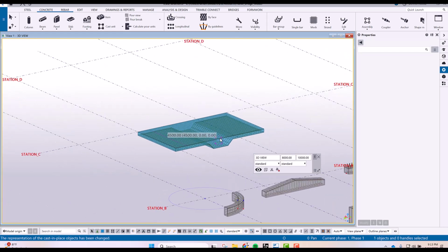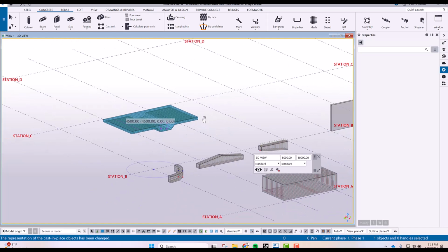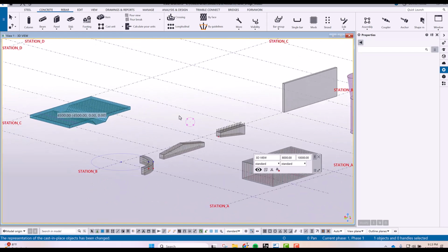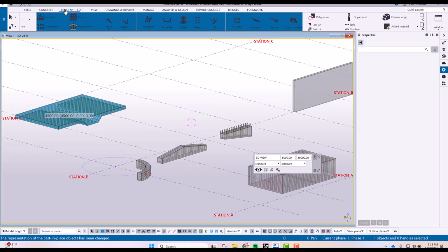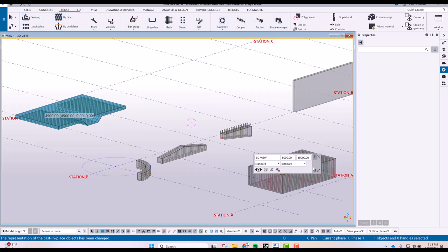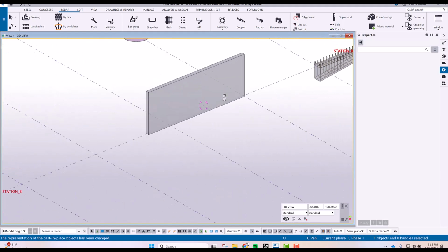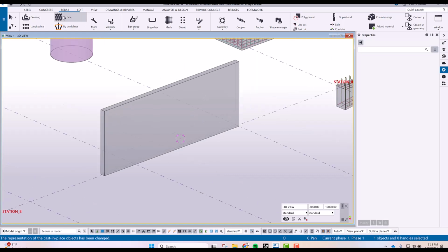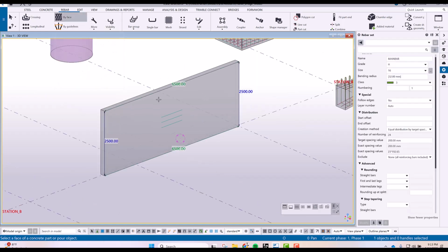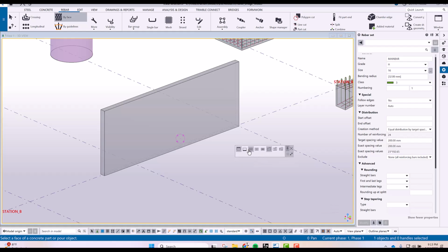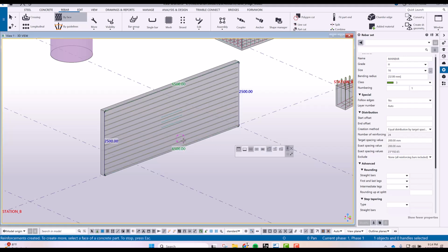Okay, and yeah, so that is how you use the rebar group or rebar set in this variety of concrete shapes. Another thing here is this by face. If you click this by face, here you can see the different options, if you want to use the horizontal or long axis, short axis, or both axes. So for long axis, just click the surface, it will be long axis.